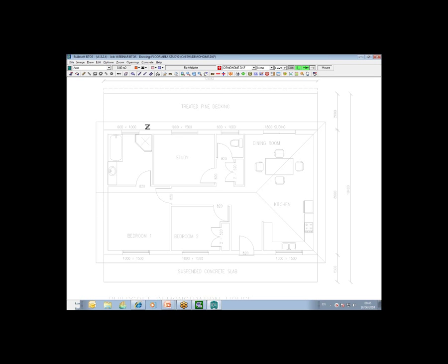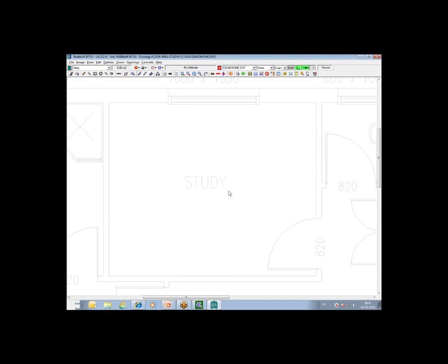Now, how it works is you can start really anywhere you want, top left, bottom right, top right, bottom left, whatever is easiest for you. You click and hold the left mouse button and you'll get an XY type cursor. Whilst holding, you drag, and then when you have the section zoomed in or highlighted, you let go and it zooms into that particular section.